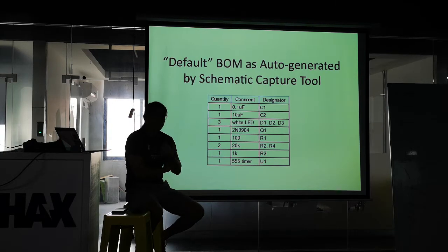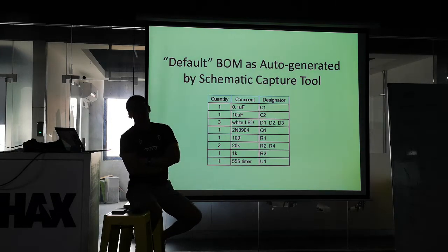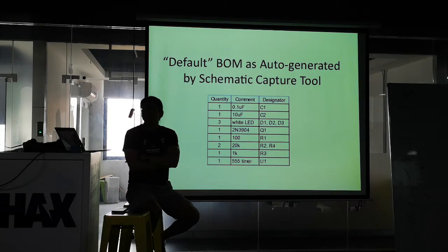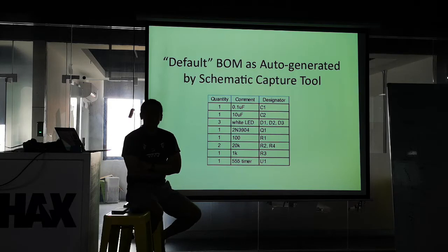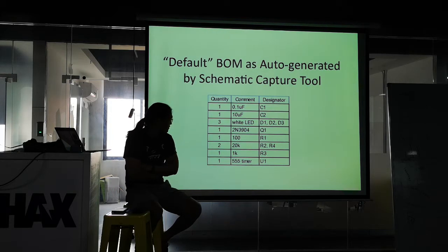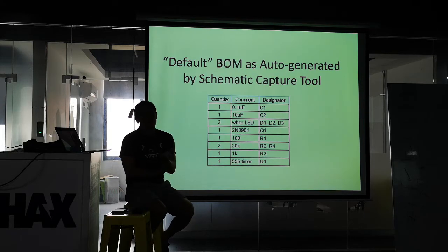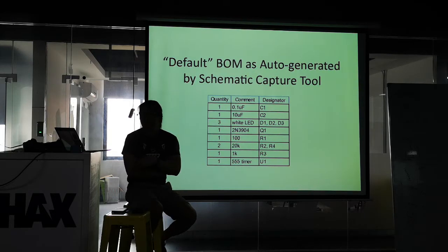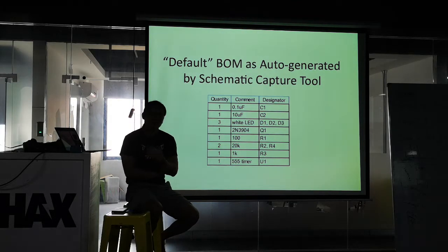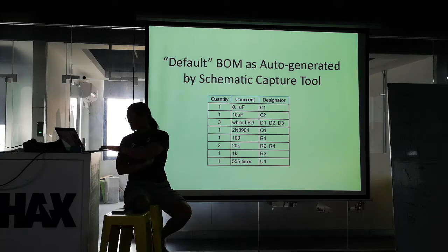And this is the bill of materials that typically will come out of an Altium tool for this, if you just use the stock library components. So everyone here would know how to build the circuit correctly. But if you handed this bill of materials to a factory here in China, you're not necessarily going to get a circuit that works. There's a lot of things missing from this bill of materials. Yes, the key information is there, but things like how big the components are and what the tolerance is are missing by default from an Altium schematic. So some of the things missing are,